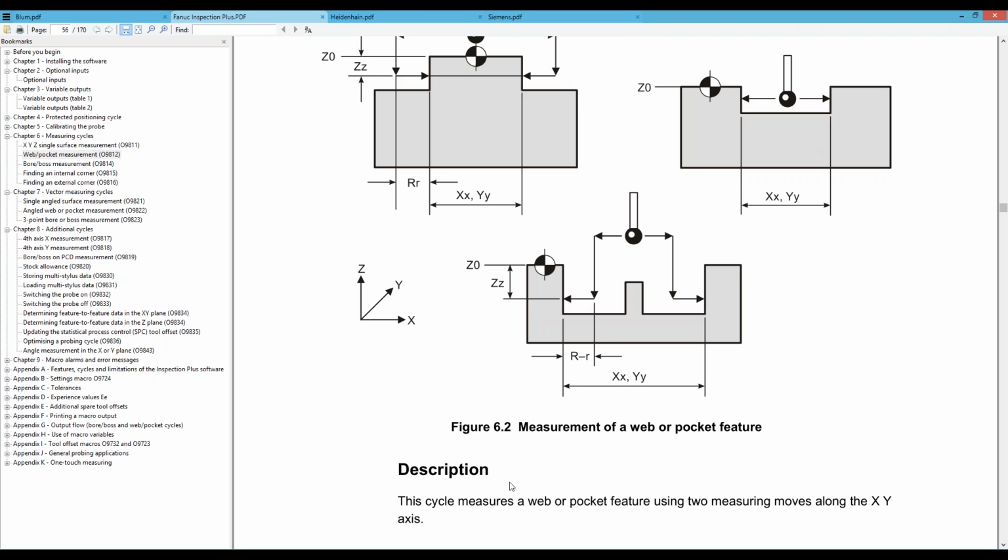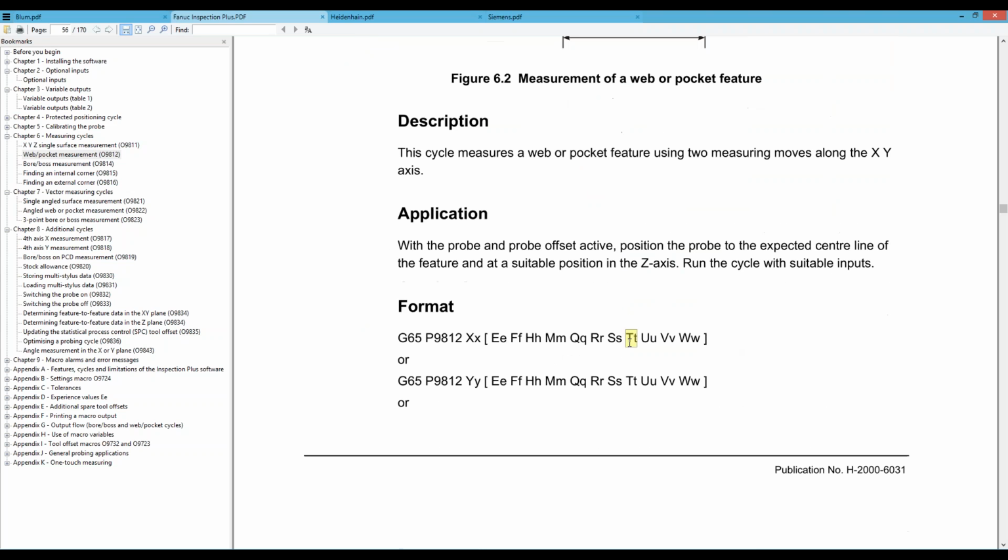The radius of the tool will be updated in the tool table. You just need to repeat the machining operation again, where you have the milling of this pocket. Again, the tool is already updated by the measuring cycle using optional input. Okay, Florian, I think his question was a little bit different. What he meant was how do you measure an in-process stock model geometry?